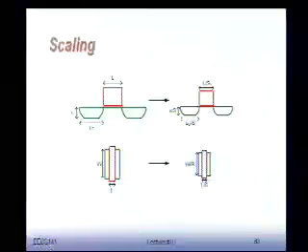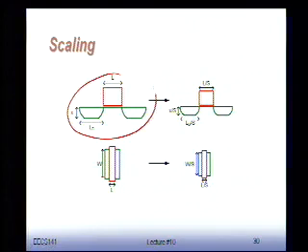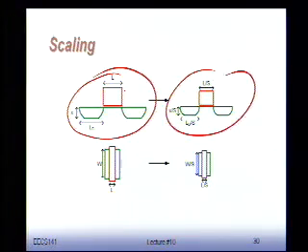Now, that kind of summarizes a little bit. So this is what scaling does. What I assume for full scaling is that all the dimensions in my transistor, if I go from one generation to the next one, I'm going to shrink everything exactly the same way. That basically means the length of the devices, the width of the devices, the junction depths, the drain regions, source regions, oxide thicknesses as well, another problem.